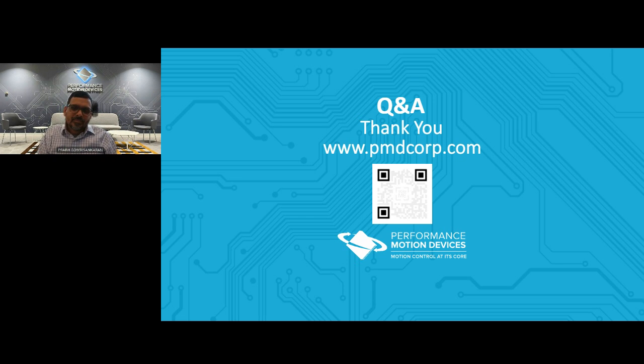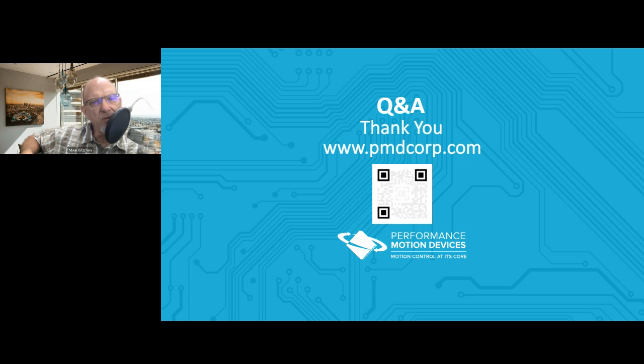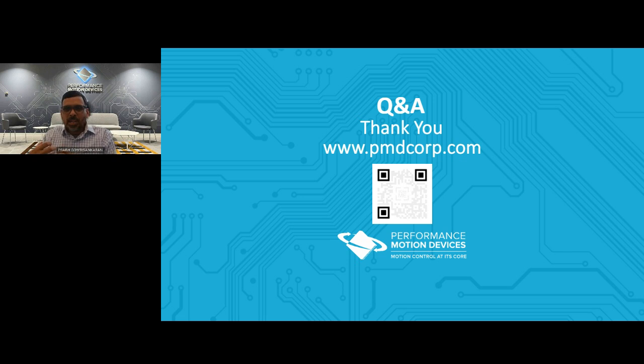Interesting. And what's the maximum number of axes then that can be controlled by one of your standalone drives? So the drive is a single axis, so you need a drive per axis. On the chip side, we have two flavors. One is a single axis chip, and the other is a 4-axis. It's a 2-chip solution, so it can do 4 axes at a time. The drive itself is 1 axis. But the drive is pretty small. If you look at our module, it's only 37 by 37 millimeter, so you can put that per axis.